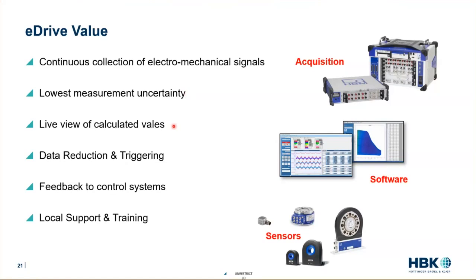We have a live view of calculated values. I missed a couple letters in there, apologies. Where you can program in things like negative d-axis current, these zero sequence voltages, these harmonics, and you can track those and watch them live and watch if they're creeping and record that as data.